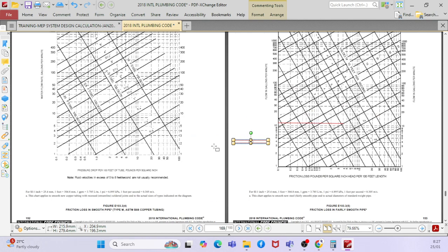Assume there is a pipe here, and you have a pump here, and you have the same pump here, and you have a short pipe here. Do you think the same flow will be here and the same flow will be here? No, because of the pressure. When water passes through the pipe, there is friction created within the pipeline. So the pressure keeps on reducing. That means it will reduce the flow and maintain a lesser flow here, and it will maintain a higher flow here because of the shorter pipeline.